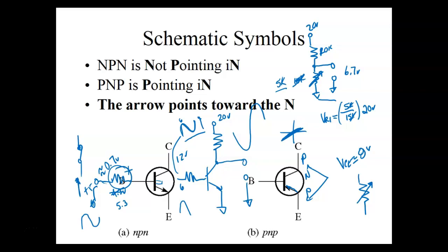So the output on this arrangement would be 180 degrees out of phase with the input. Does that make any difference? Well, as far as sound goes, it makes no difference at all, as long as your right channel and your left channel have the same phase shifts through the circuit. So what determines what sound you hear?